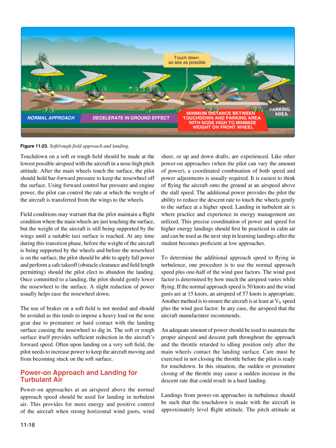At any time during this transition phase, before the weight of the aircraft is being supported by the wheels and before the nose wheel is on the surface, the pilot should be able to apply full power and perform a safe takeoff, obstacle clearance and field length permitting, should the pilot elect to abandon the landing. Once committed to a landing, the pilot should gently lower the nose wheel to the surface. A slight reduction of power usually helps ease the nose wheel down.